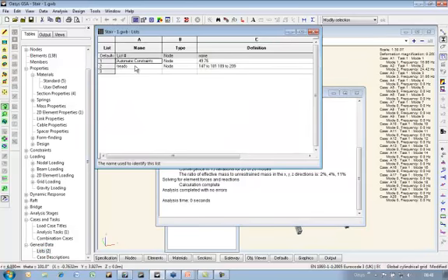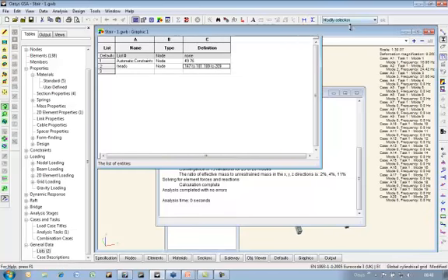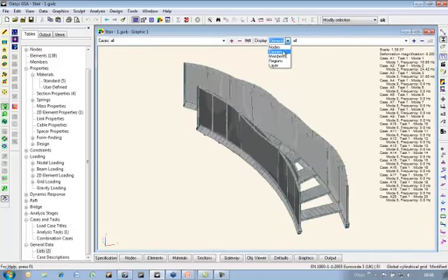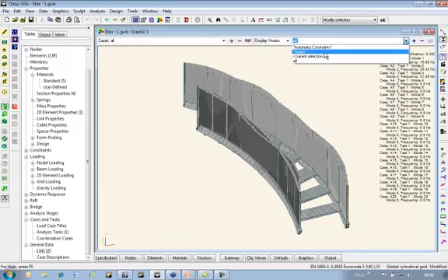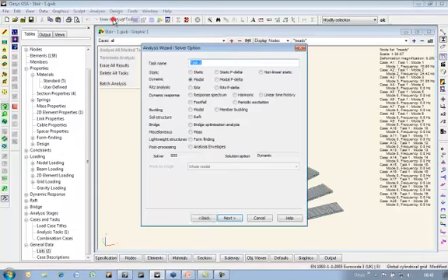Now I have set up a list of the tread nodes already, and these treads, this is where people are walking, this is where the response is felt. We're not interested in the vibration of the balustrading itself. So I'll do a new analysis task on this, which is a footfall.